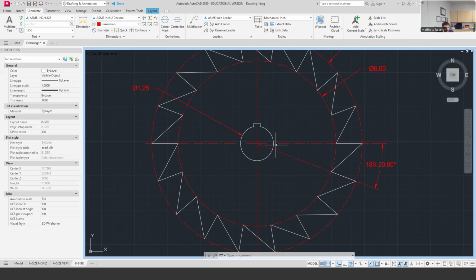Engineering is going to tell us how big of a diameter we need to transfer this much torque to something, right? The diameter has to be an engineered design size to withstand that. So engineering is determining our diameters, and our diameters are determining the keyway key seat relationship.